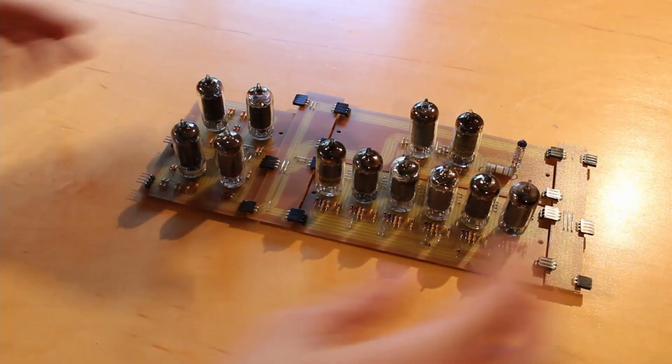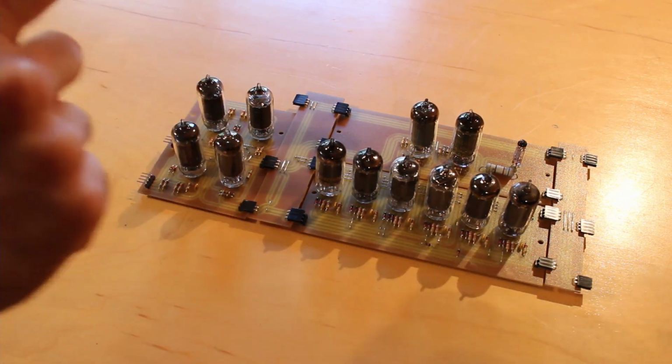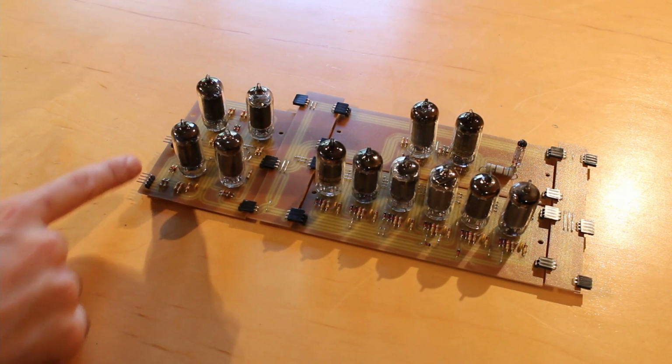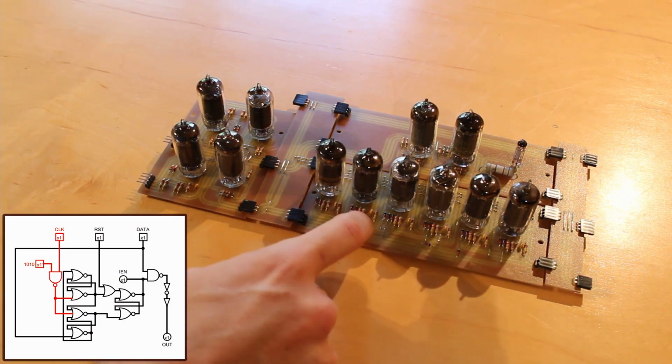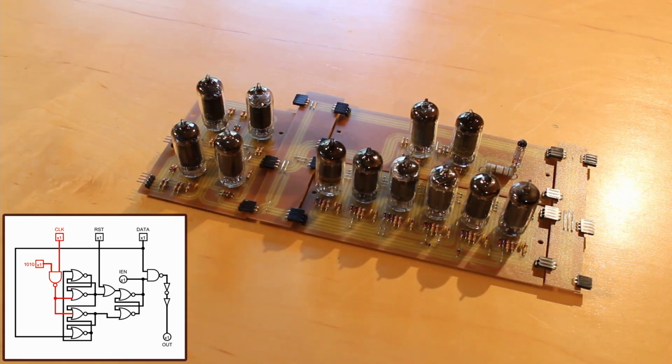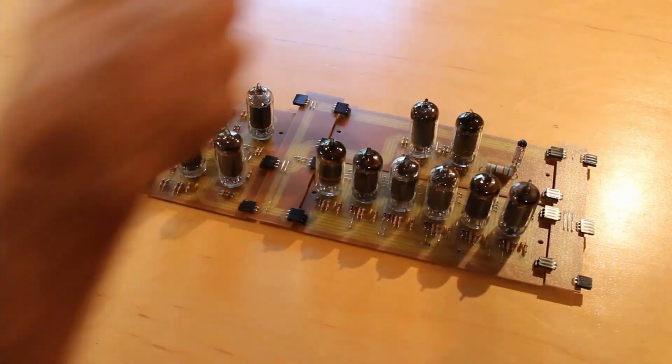All right, so we're getting pretty close to being able to test this, but we need to now sort out the inputs into this one. And we have 4 separate inputs that we need to figure out. For our first NAND gate right here, which is going to be the clock signal that initiates our input enable register over here, we need the actual clock coming into it as well as the instruction register control line 1010. And 1010 is going to come down from way off to the right and snake across the top of all of these boards.